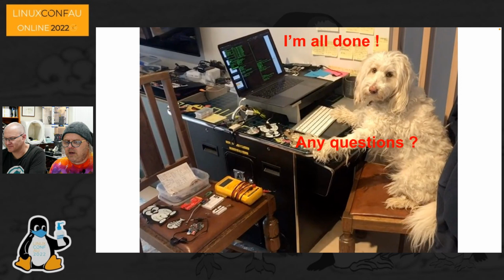Actually, we already do have the ability to send wishbone commands that write to the I2C bus. Yeah, I'd say it's potentially possible to use wishbone commands to talk to the I2C bus with the ESP32. So it'll take a little bit of work, but I can see it's possible.